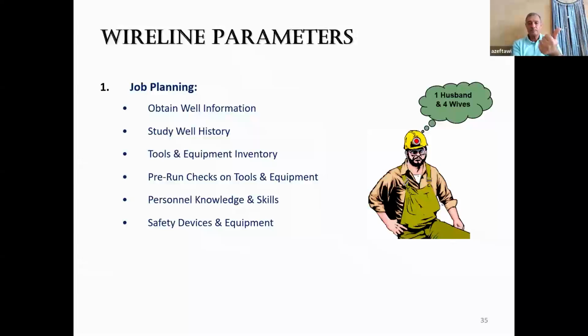One certified but empty. One certified but has a broken gauge. One certified but has no handle. One certified but has no hose. So they are all certified, yes, but none of them is working. So you have to check visually.